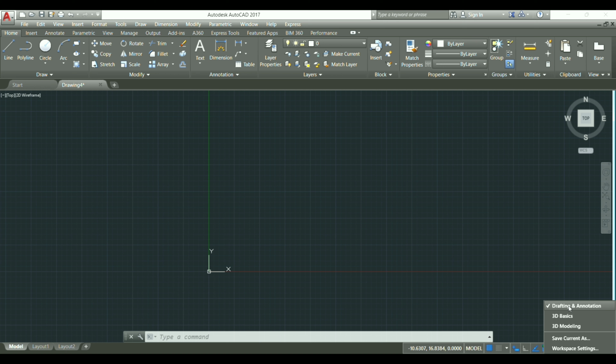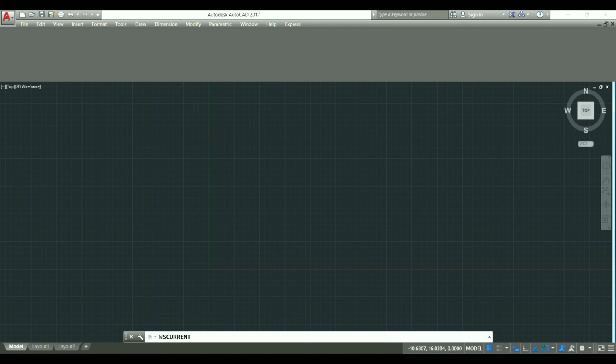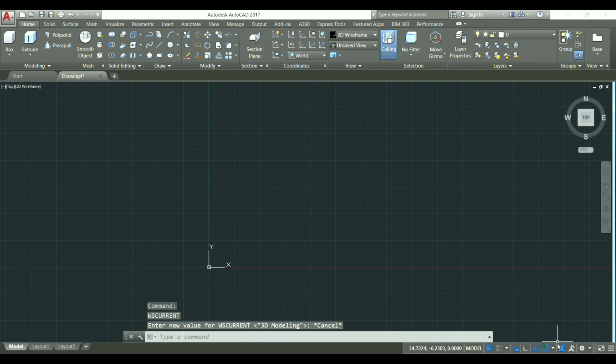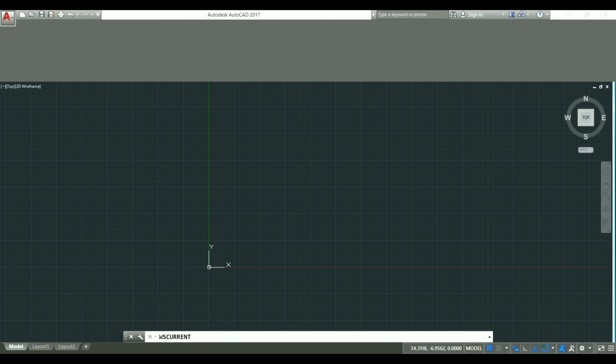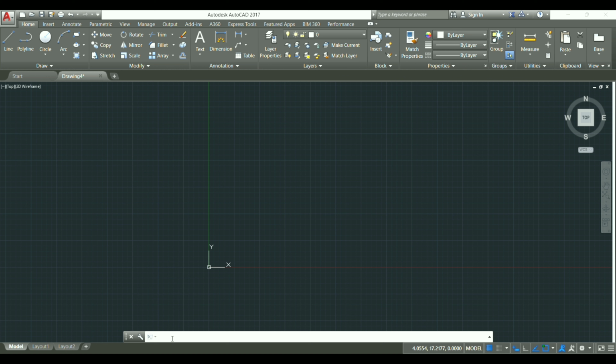Basically, it is used when you are doing 2D drawing. But let's change it to 3D Modeling by clicking on it and selecting this choice from the drop-down menu. 3D Modeling is used for 3D drawings. These options will allow us to use all the 2D and 3D tools required for our drawing. In the command bar, the user can enter commands manually by typing them here. It also lists the order of the required steps to execute any given command, plus some extra tips.